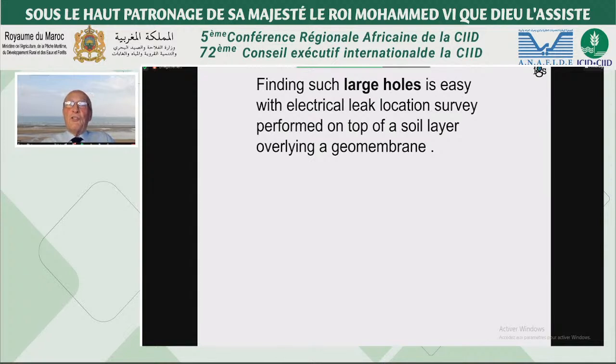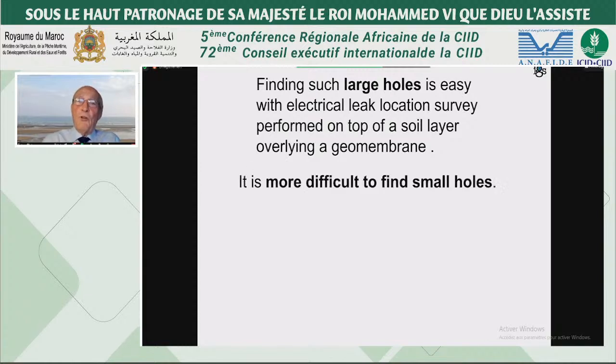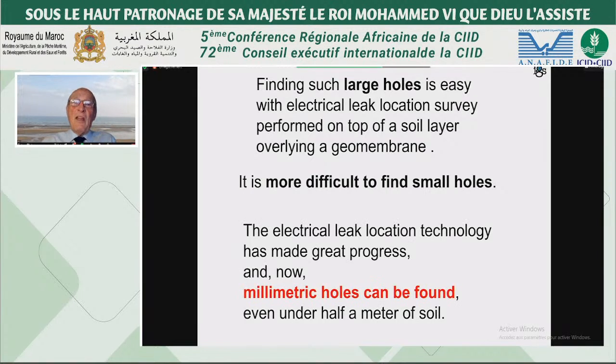Finding such large holes is easy with electrical leak location survey performed on top of a soil layer overlying the geomembrane. It is more difficult to find small holes, but the technology has made great progress, and now millimetric holes can be found even under half a meter of soil.